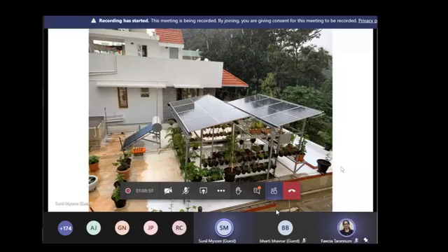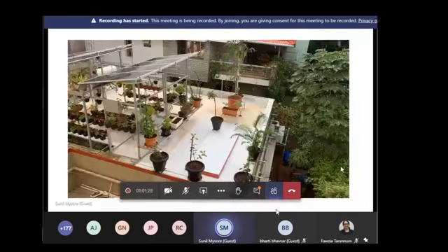So this is actually the catchment. You can use it for many other purposes. Even in this catchment where I'm talking, there's a lot of mud runoff, because you can see there are so many pots. To give you a number, there are 147 pots here. So you can imagine the amount of silt which comes out from this. Of course, you have to do some amount of filtration, dispersal, separation, and everything, so you have to factor in all those things when you go to design. I am just showing you; I'm not telling you this is how it has to be. But it is also possible. Ideally, I would want the roof to be looking like this, but if you have it like this, there is no problem. I don't know if this can play or not, but this is a small video.